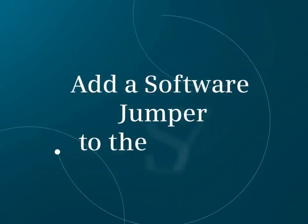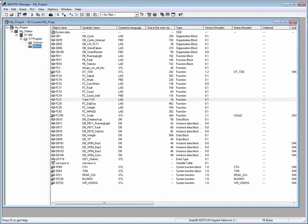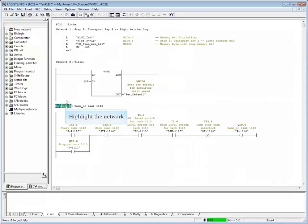In this video, you'll see how to add a software jumper to S7 code. Begin by opening a block. Let's open FC21. Select Network 3. Click the glasses to turn monitoring on. Input 1.5 named LL1110 has failed.